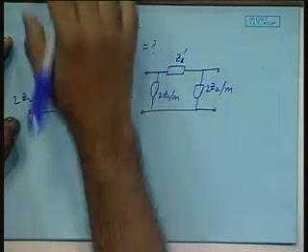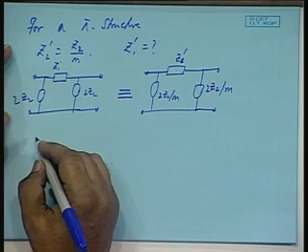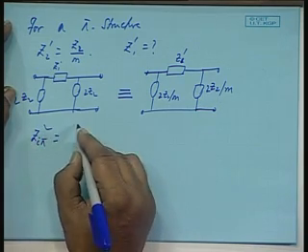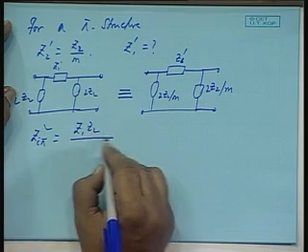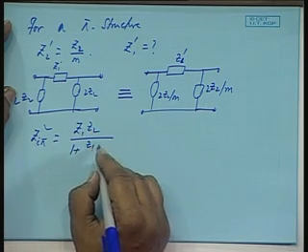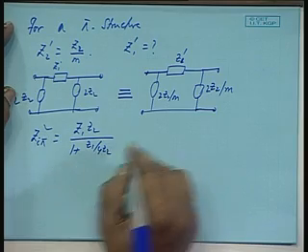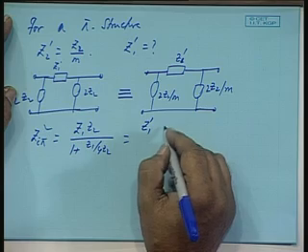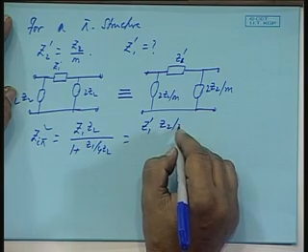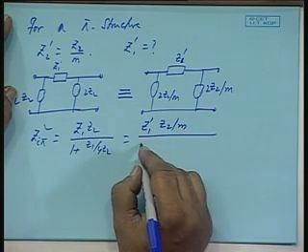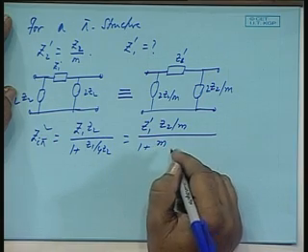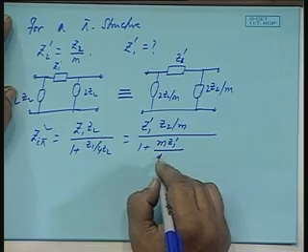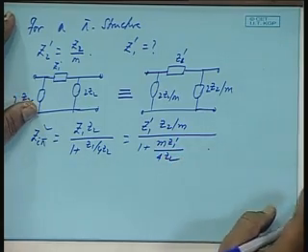So, once again we equate the two characteristic impedances. So, Z I pi squared, the expression is Z1 Z2 by 1 plus Z1 by 4 Z2, and on this side you will have Z1 dashed, Z2 dashed is Z2 by m, 1 plus m Z1 dashed by 4 Z2.